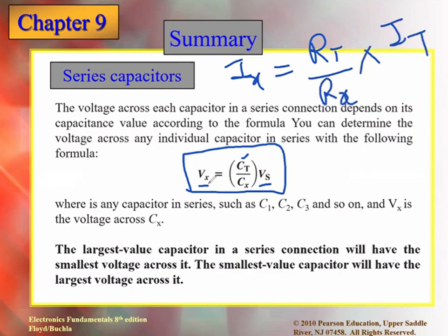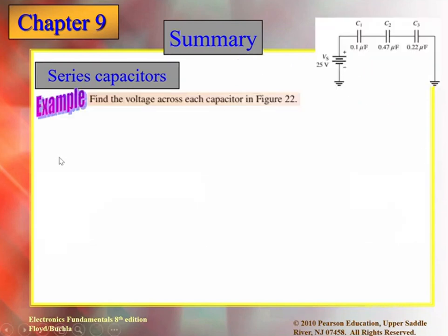So we replace R by C and we replace I by V. As I told you, what you learn for the resistance, here it is going to be opposite. So this way you can easily memorize, and it is better if you keep noting here. Write a note for your reference: it is similar to the general current divider formula for a resistive circuit. But this is so easy for you. You can keep writing the notes here. Okay, so this is done.